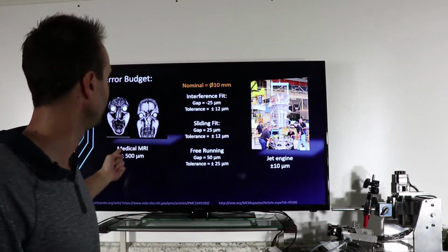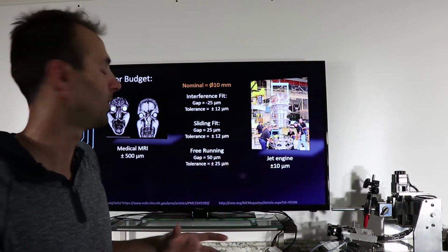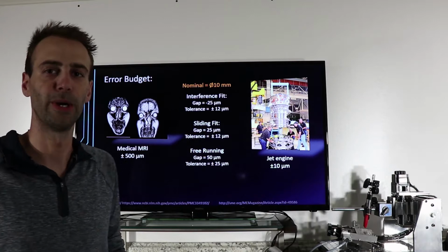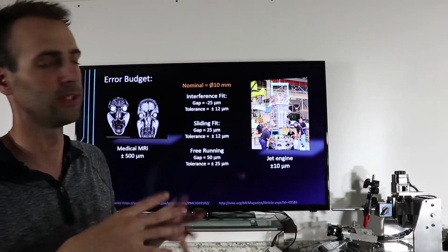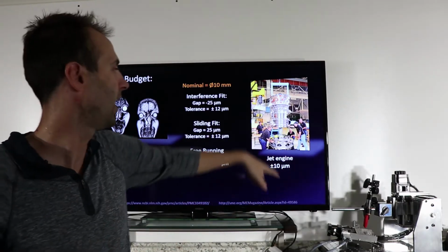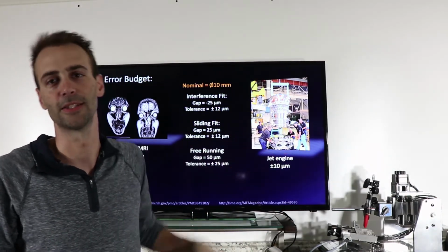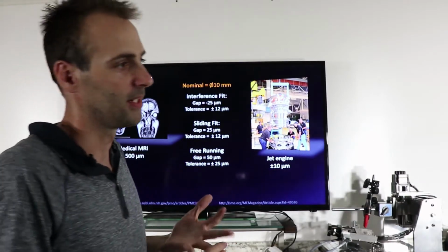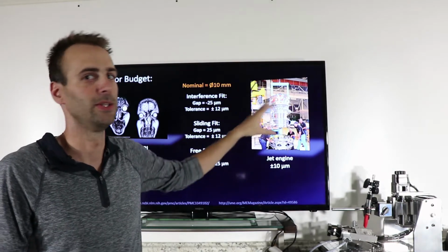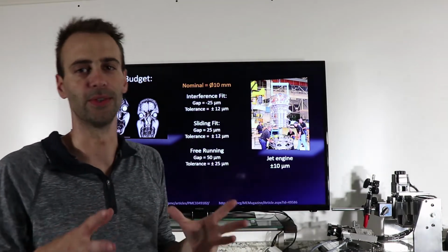So again, am I making pretty pictures or pretty parts in a design studio? I'm on this spectrum. If I'm making a steam engine or boring out a piston in an engine or doing journals or anything like that, these are the types of tolerances that I see. And if you're off the deep end in high-end manufacturing and you want to split hairs, you can do it. But this space here is super expensive, with super highly specialized machines. So yeah, you can make machines do this, but I recommend shooting for this, and if you could squeeze these tolerances out, do it, okay?